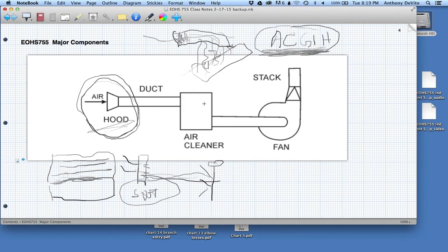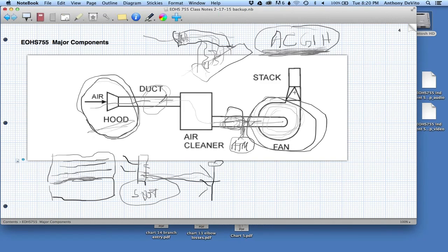Okay, so the next thing that we have is ductwork. We have a hood, and we need some way to connect it to a device that's going to exhaust the air it's pulling along with the contaminant and exhaust that outside of the worker's environment. So that ductwork is going to go over to a fan. That fan is generating a negative static pressure. It's generating a suction to pull that air in. We know that if we put a hole in this ductwork on the suction side of the fan, it would pull air in, because the pressure in there is lower than the atmospheric pressure outside of the ductwork. So we're pulling air through that hood, using the ductwork as a conveyance to the fan. And the fan is what's giving us the energy required to produce that suction, that negative static pressure, and to discharge the air outside of the building up the stack.